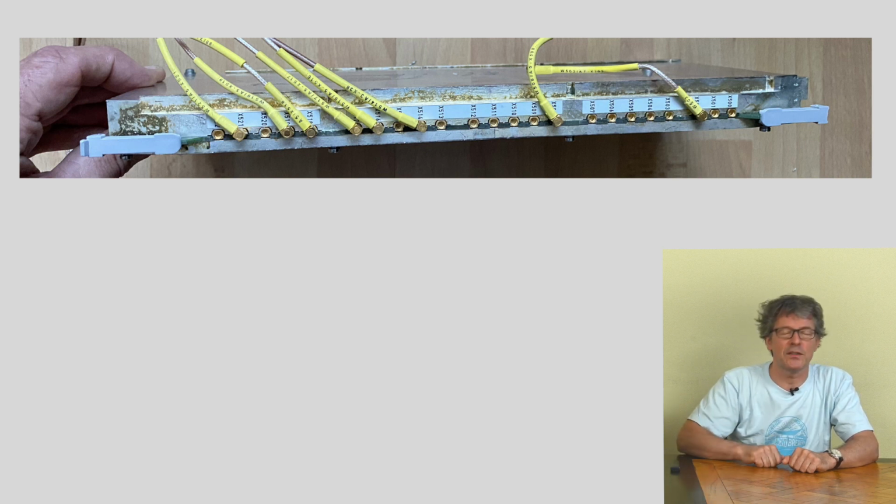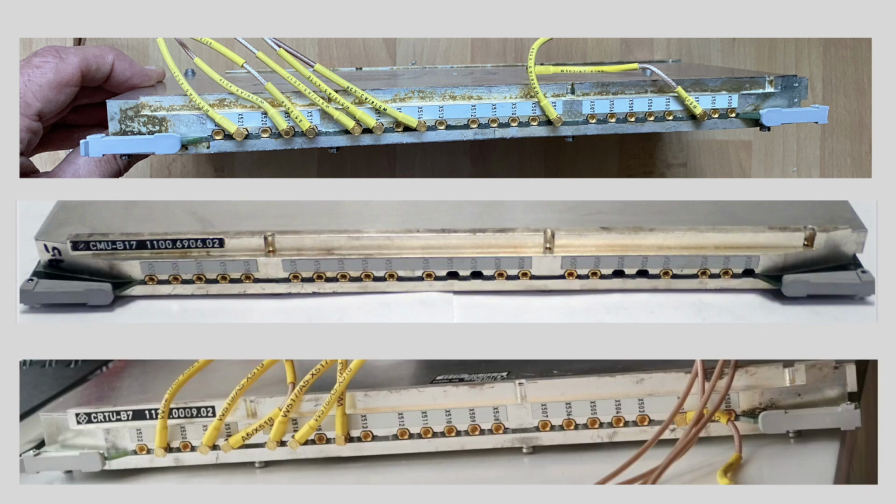Now let's take a look at 2 other pictures of units that I got from the internet. In the middle you see a B17 unit, the one that's supposed to go into my device. At the bottom you see the B7. And why do I think that I got a B7 in the end? Well, look closely at the connectors, at the sockets that are present on the devices. You will see that on the one in the middle, a couple of sockets are missing. This is basically because the B17 is a single channel device. It does not have all the same functionality, and I think for that reason it misses some of the sockets over there.